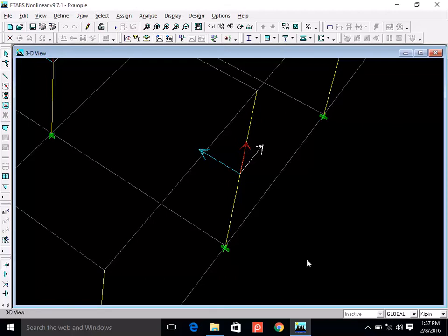Okay. There may be a situation where on this side of the beam you have different loading. Maybe there is a store and it is heavily loaded, and on this side you may have an office. Load is less. So when there is unequal loading, although the dimensions are symmetrical, the magnitude of loading is unsymmetrical, then you will have bending moment about this axis as well, right? So the point I want to make is that you cannot make a universal statement that an edge column is always a uniaxial column. Generally it is, but when there is unsymmetrical loading or unsymmetrical dimensions, then an edge column may also have biaxial bending.